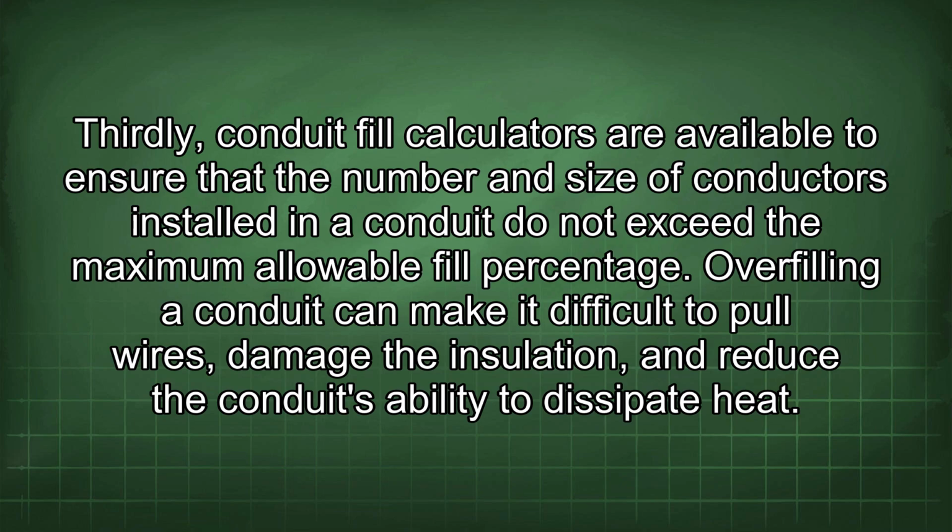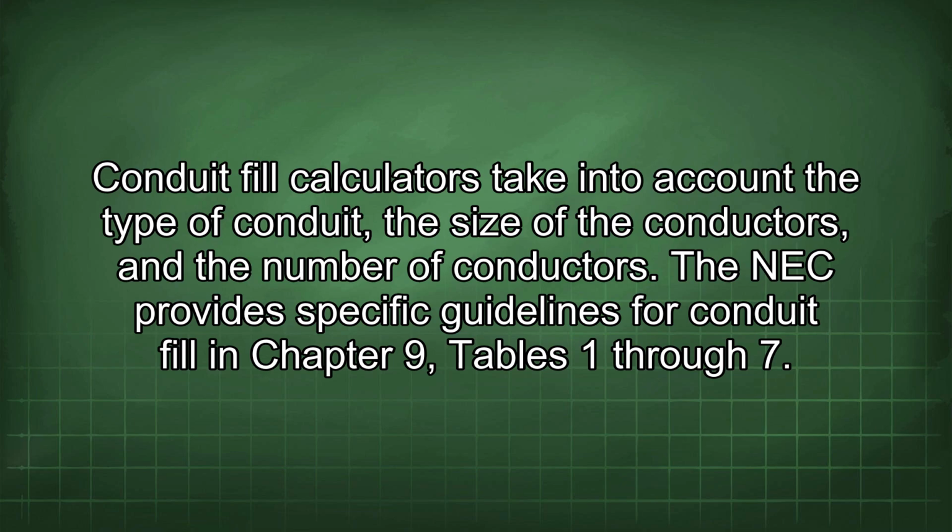Thirdly, conduit fill calculators are available to ensure that the number and size of conductors installed in a conduit do not exceed the maximum allowable fill percentage. Overfilling a conduit can make it difficult to pull wires, damage the insulation, and reduce the conduit's ability to dissipate heat. Conduit fill calculators take into account the type of conduit, the size of the conductors, and the number of conductors. The NEC provides specific guidelines for conduit fill in Chapter 9, Tables 1 through 7.